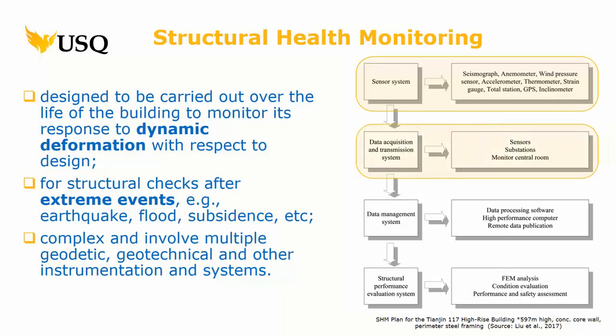So when we get to data acquisition, it's how we acquire it. Traditionally, that would be by measurement and then by booking the measurement or downloading it. Now, more commonly, it's by wireless systems, or in a lot of buildings, they actually have built-in fibre optic cable throughout the building. It's not just for the occupants, it's actually to keep the sensors linked together. The reason for fibre optic is it's very fast, so it can handle real-time systems.